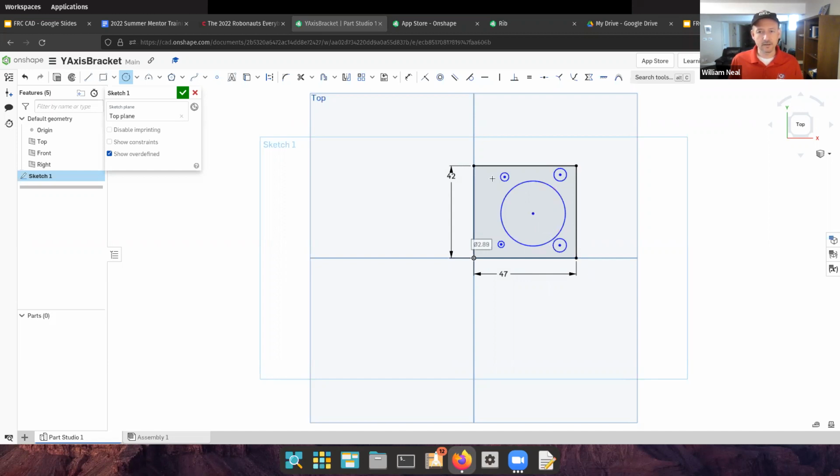And since the 42 millimeters is the sort of footprint of the motor, this 5 millimeters is going to be for another section of the part coming out in a third dimension here. So I'm going to constrain these dimensions horizontally and vertically, holding down my shift to get 2 pieces at a time. That's 19. Half of 42 is 21. So it's going to center it where I want it to be. There's the horizontal distance, and the vertical distance also should be 21. Good. The radius of this, if I recall again, it should be 30.